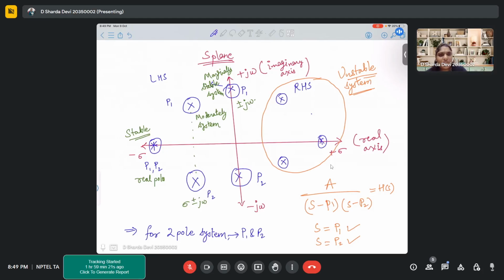Now, if it is a single MOSFET, you have fabricated that MOSFET. You are using that MOSFET, and that MOSFET has that surface exposed. So there will definitely be a junction formed, and that junction will contribute to your capacitance. So that junction needs to be considered. So that's why we considered that.